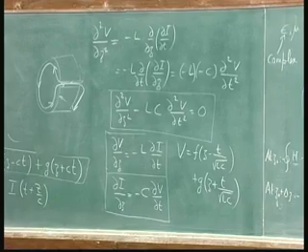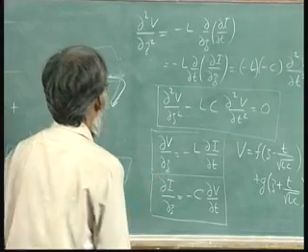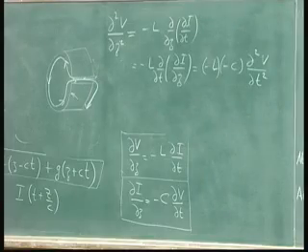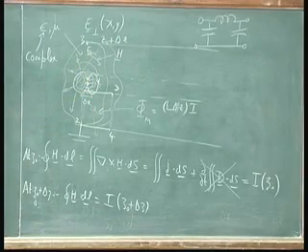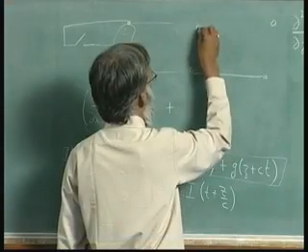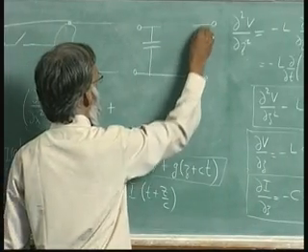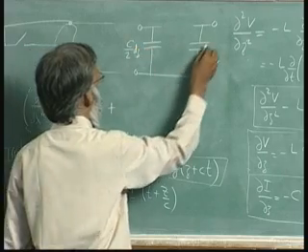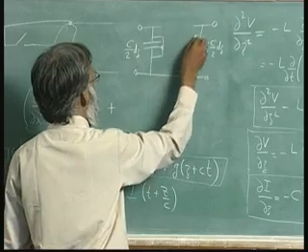So the equivalent circuit will not just be a capacitance, there will also be a resistor in parallel to the capacitor. So you will start having a resistive current between the inner wire and the outer wire. So in place of just having capacitors, each of which has a value C over 2 dz, you will also have a shunt resistor.